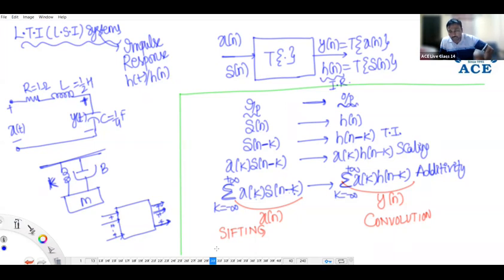So roughly I explained how we got the convolution relation. We got convolution because of the shifting property only. As the shifting property states that any signal can be produced as a sum of impulses, we are denoting an LTI system as impulse response.